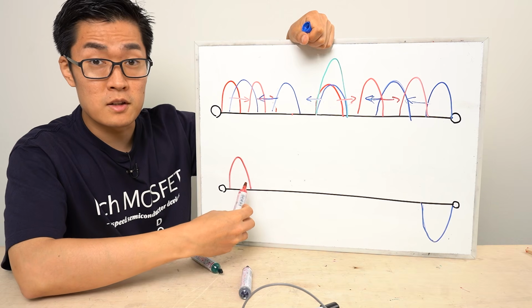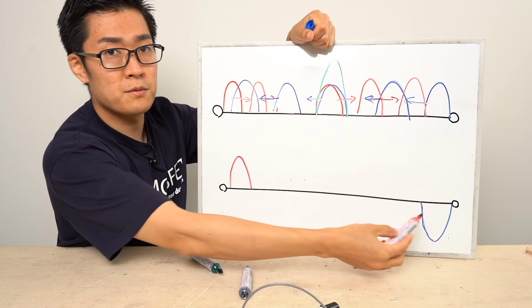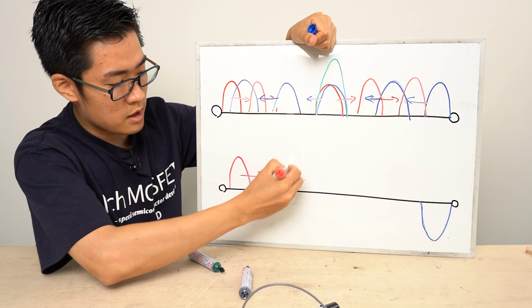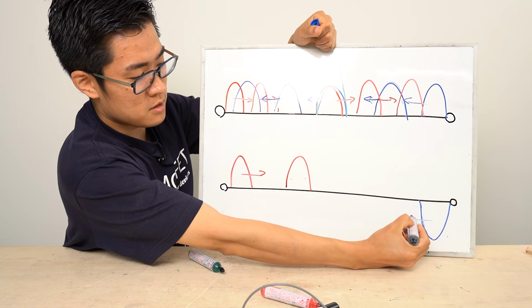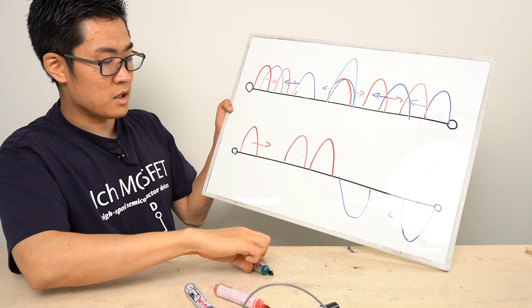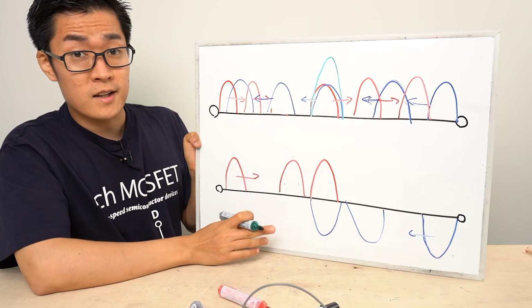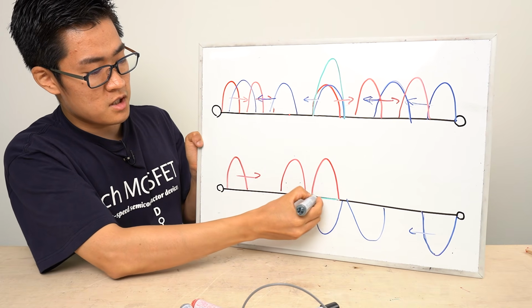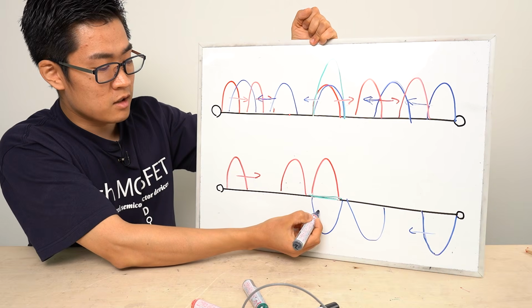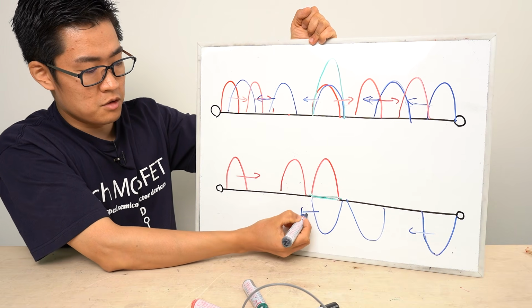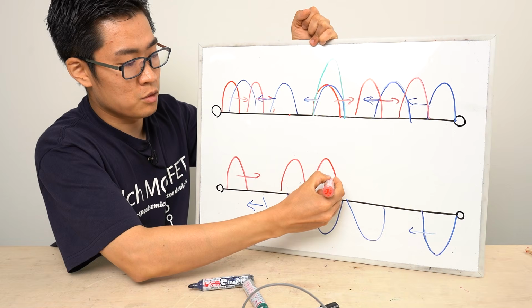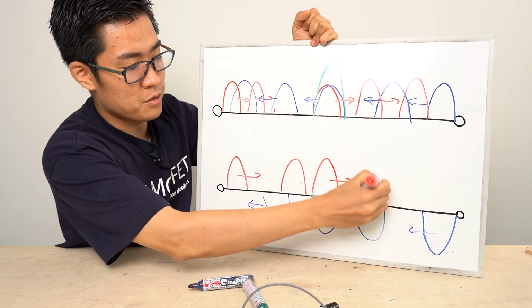If a positive voltage is applied to the input terminal and a negative voltage to the end terminal, it works the same way. The voltages keep traveling. The same goes for the voltage applied at the end terminal. And here, right at the midpoint, the waves overlap with each other. Even though they overlap, they cancel each other out because one is positive and the other is negative. As we saw, the amplitude is zero. After the overlap, the signal sent from the end terminal keeps moving along its path. And the signal from the input terminal also continues traveling in its original direction after passing through the overlap.